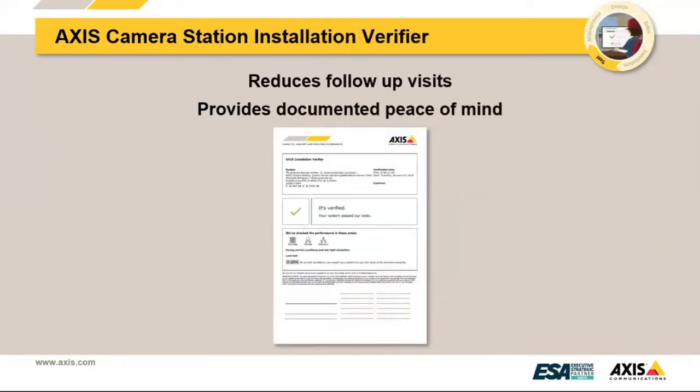Also, another thing that I think is very unique to Axis is our installation verifier. Our installation verifier is a stress test that Axis Camera Station can run on the entire solution. So it's only going to work with Axis cameras because what we do is we upload a small little ACAP, small little program to the cameras that says, open up the floodgates. Because think about this, if you do an installation at a school, you do the installation during the summer when no kids are there.